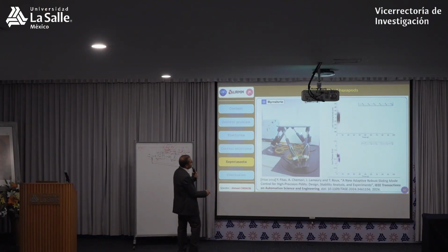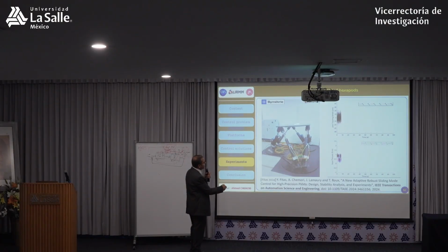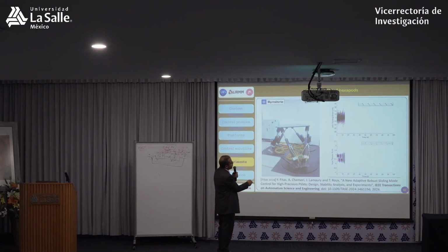Here it's the motion in the nominal case, there is no payload. Look here at the tracking errors. It's the joint tracking errors in each joint. Look at the unit, it's a micrometer. Look at the maximum, like 25 micrometers as maximum tracking error.